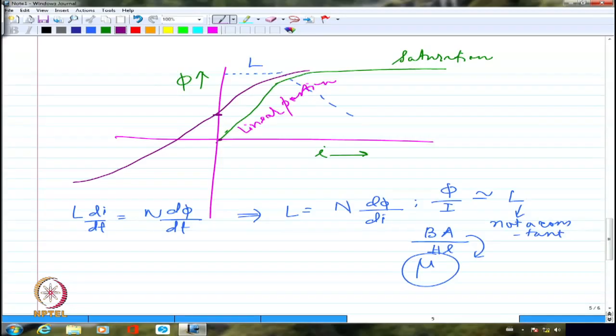That is remaining. So it is known as remnant flux. And then it will reach saturation on the other side when I sufficiently increase the current. Then it is again going to go through the same kind of movement when I try to increase it from minus 10 ampere to plus 10 ampere.